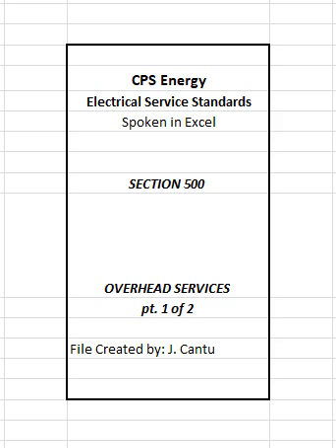Attachments to building walls shall be made such that the horizontal angle between the service drop conductors and the building wall shall be a minimum of 45 degrees. The point of attachment for the service drop conductors shall be so located as to be accessible from a ladder placed firmly on the ground and against the building.